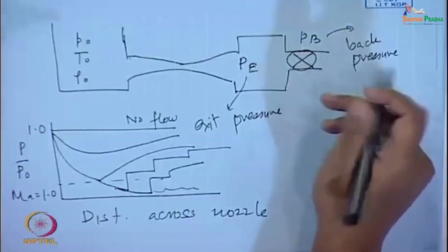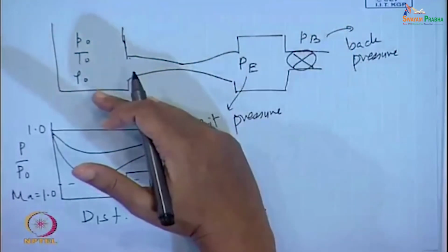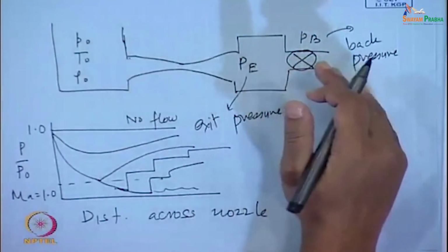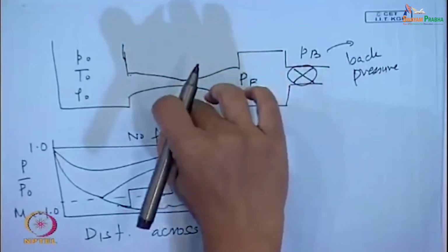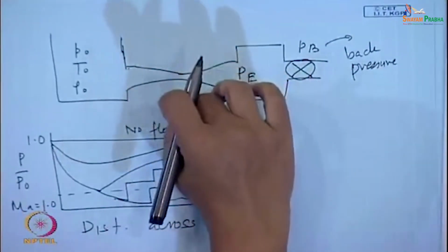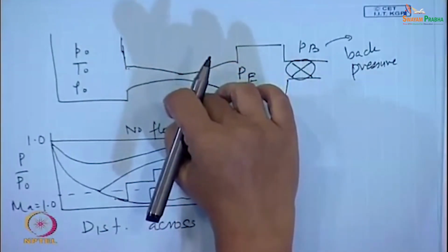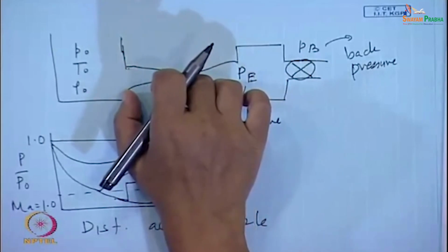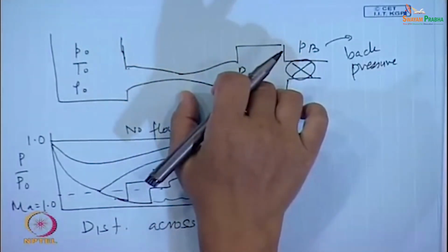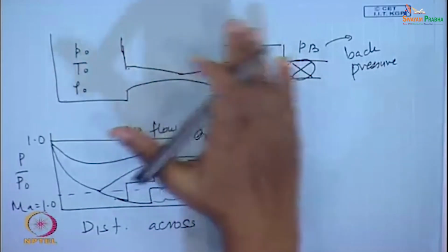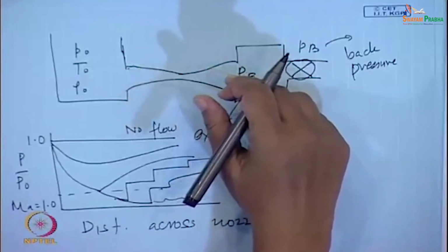Okay. So, the same thing happens, but in this particular case we can go from the subsonic to the supersonic zone, but that too only till a particular point when choked flow conditions have been reached here. The moment choked flow conditions have been reached in the neck region, we cannot do anything more. Although the flow in the upstream region is not affected, in the downstream region we find normal shocks are there and these shocks start propagating and the flow rate cannot be increased any further.